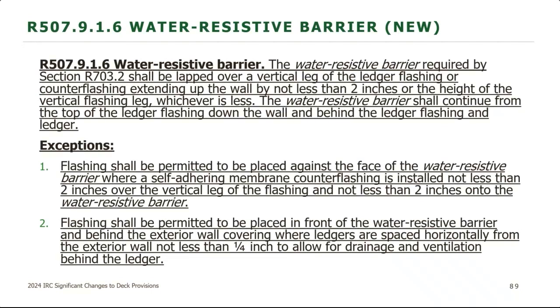When they put this into the code, they realized that a lot of people had different methods for flashing and providing the water resistant barrier around ledger boards. So they wanted to maintain a little bit of flexibility for people who are doing other methods that have been working. So you can also use that self-adhered membrane.